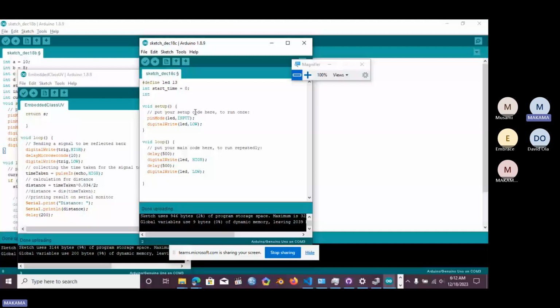It is in milliseconds, so if you say 1000, it's not that the system will wait. The system will keep on executing its void loop function until the Arduino reaches 1 second after being on, then that line of code will start operating. So we are going to use 0, which means immediately.